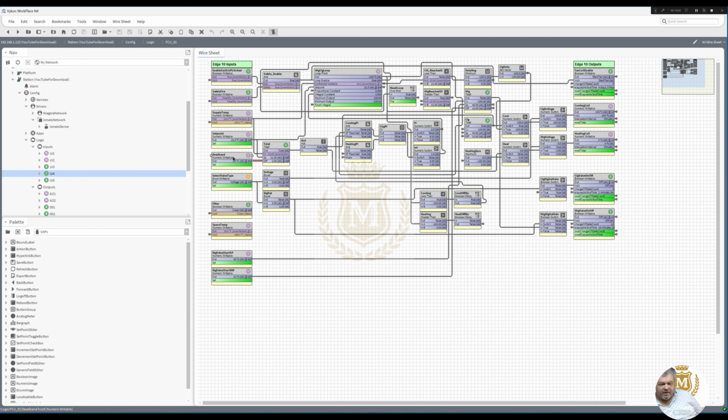We've got a dead band of 2 degrees there. So that differential in the T-stat, that 2 actually doesn't mean 2 degrees either way of the set point. You actually divide that by 2, so that's 1 degree differential of the set point. So just because you see a 2 there, it's actually 1 degree either side. So if it was a 4, it'd be 2 degrees either side.